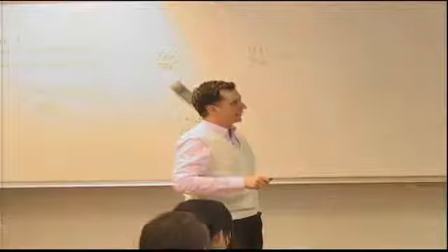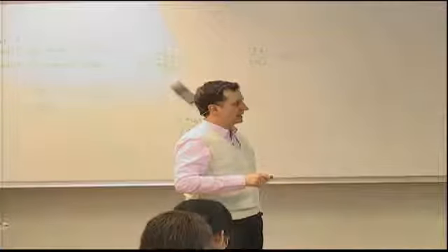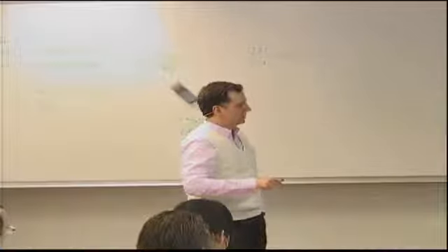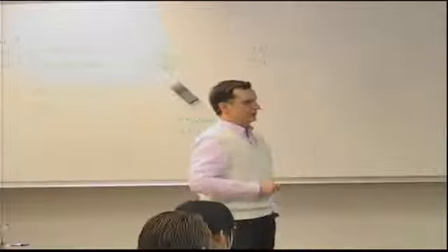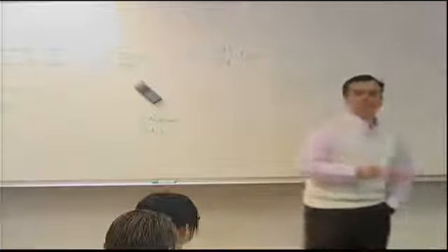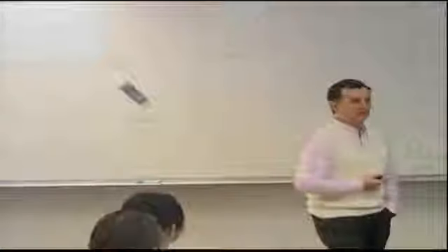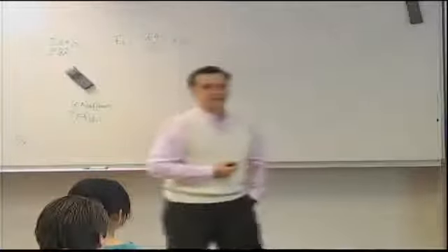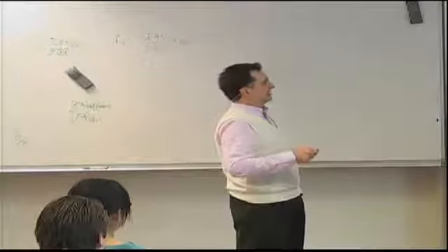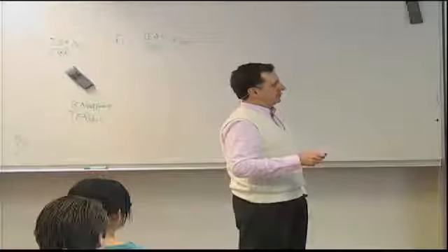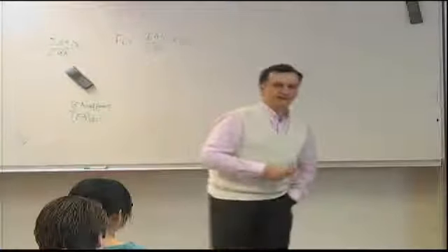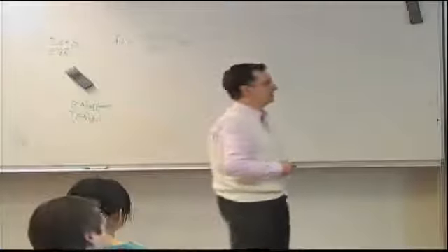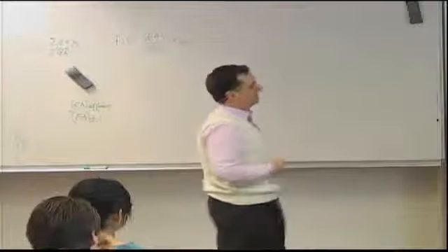We discussed what happens in the regions of pockets that are created because some plies terminate, some turn around, and some are continuous below. And we showed last time that you can get a significant load capability, up to 30%, maybe even more, if you make this filler material a unidirectional tape, which typically has fairly high stiffness. So now our update says wherever we have these potential pockets or void areas, we fill them with filler, and let's even say that it's going to be unidirectional tape strips.